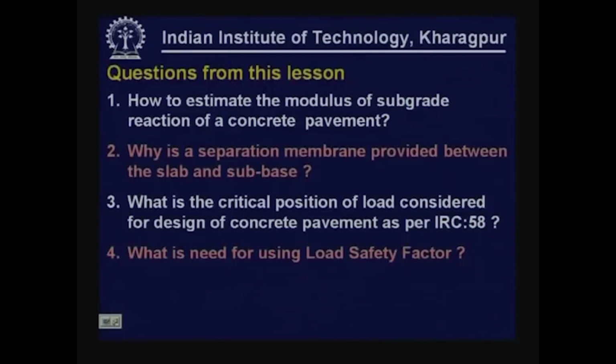These are some questions from this lesson. Answers to these will be provided in the next lesson. How to estimate the modulus of subgrade reaction of a concrete pavement? Why is the separation membrane provided between the slab and subbase? What is the critical position of load considered for design of concrete pavement as per IRC 58? What is the need for using load safety factor in the design of concrete pavements as per IRC 58/2002?